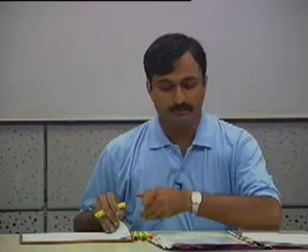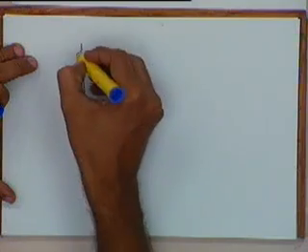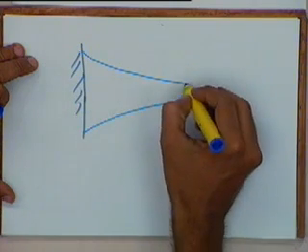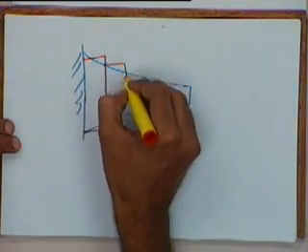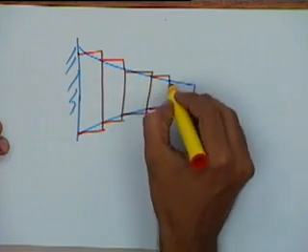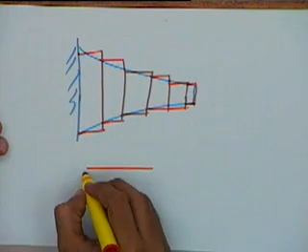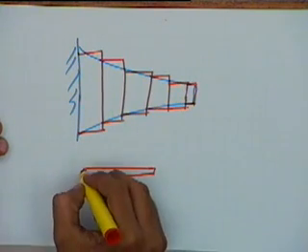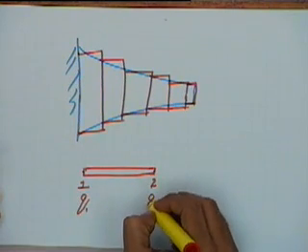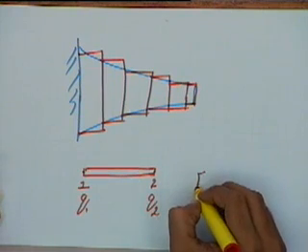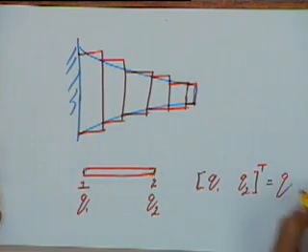Now if we talk of one dimensional problems, we formulated the one dimensional problem like this: if we take a body like this, we split it into a set of 1D elements like this, and if you take any individual element of uniform cross section having two nodes 1 and 2, we said that it has a displacement given by q1 q2, or the element displacement vector we said was q1 q2, which we are representing as the vector q or the matrix q.